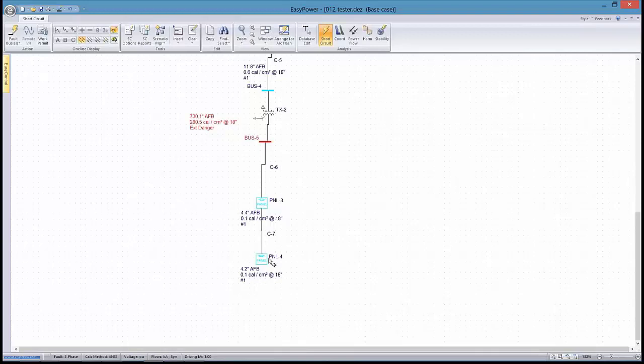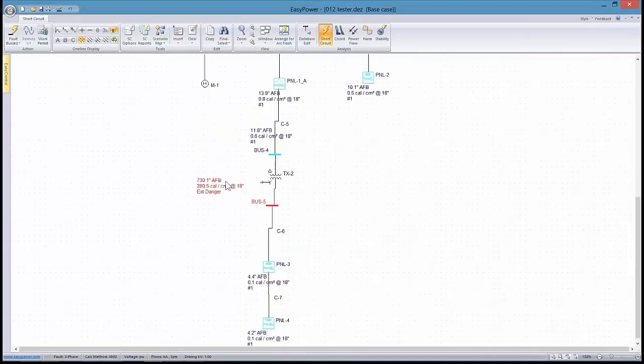So there is going to be some error built into these single phase calculations, and a case in point is, especially at lower voltage, we could have artificially high incident energy calculations because of the IEEE model being a little bit skewed towards the medium voltages between 400 and 1,000 and less accurate in less than 240 volt range.